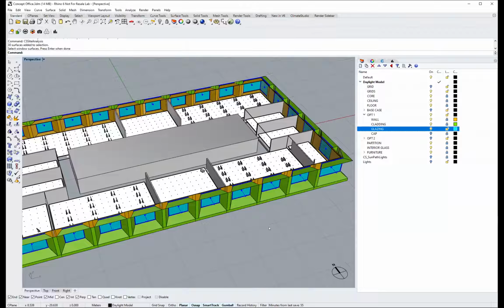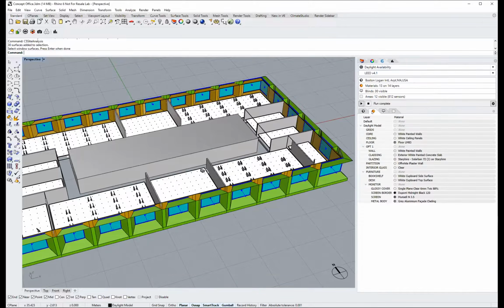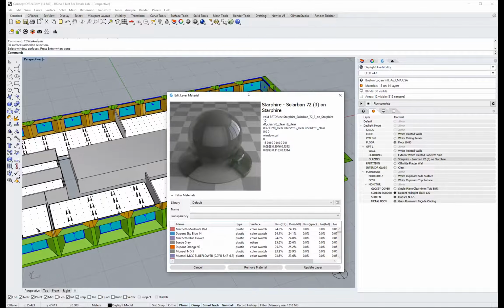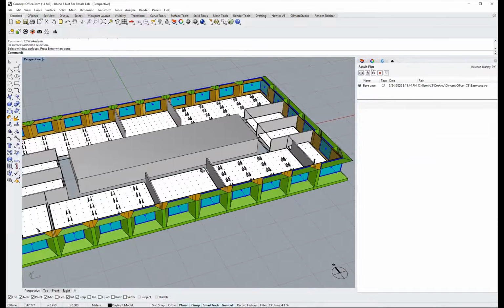I'm also providing shading against the direct component a little bit and discriminating between high angle summer and low angle winter sun. So at this point, letting in more light through the glass would be better. Here I've switched my glazing type from something with about 40% VLT, which might be reasonable for imagining a fully glazed tower, up to about 60%. So that's the other thing I've tweaked.